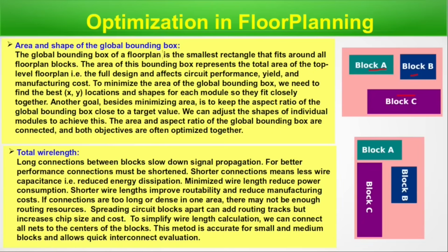Area and shape of global bounding box. The global bounding box of a floor plan is the smallest rectangle that fits around all floor plan blocks. The area of this bounding box represents the total area of the top level floor plan, that is the full design, and affects circuit performance, yield and manufacturing cost. This is the smallest rectangle that fits around the floor plan blocks, the full design, holding all the macros.